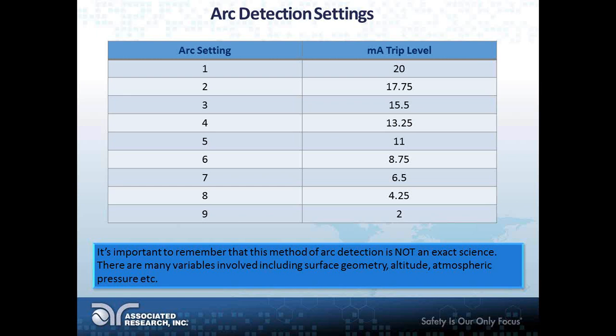Just because your product fails with an arc fail, if you are using it, doesn't mean you have an insulation failure. Now, if you have arc fail on and you get an arc fail, and then you turn it off, and you go back and you test again, and you get a breakdown or something along those lines, okay, yeah, then it has given you a heads up like, hey, you might have an issue here. But a lot of times we'll get calls from customers saying they keep getting arc fails.